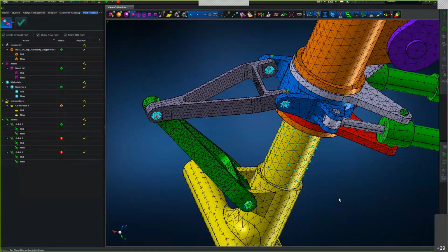One thing to note is that with the manual glue, the elements can be distributed across multiple parts. So the elements can be distributed anywhere in the model. They don't have to be in a single mesh body. They don't have to be even in a single part. So you can glue regions from 3 different parts to regions of 2 different parts. It's completely arbitrary how you do the gluing.